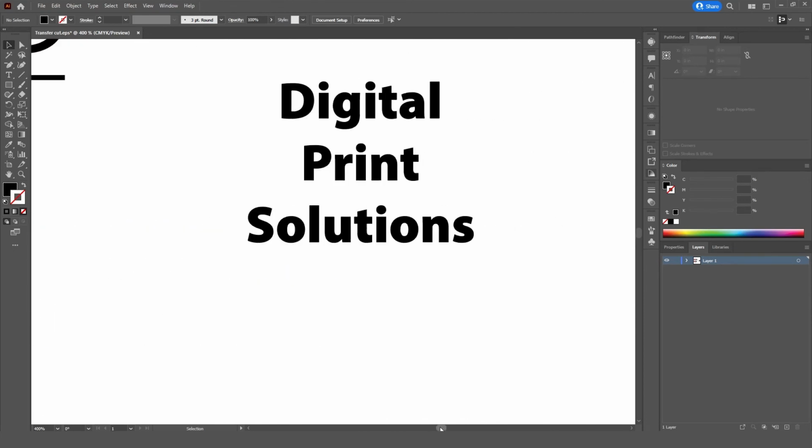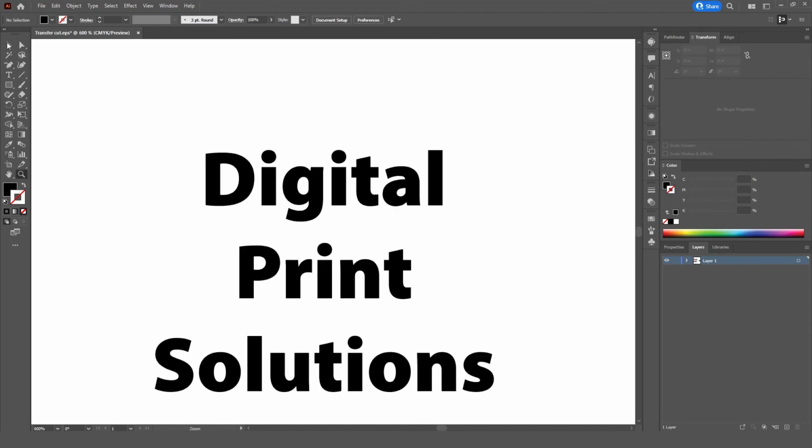The last problem we run into is when we're cutting out the lettering like this. The pixels within the letters can also be too small. In this case, these letters are only about 0.2 inches tall, so the pixels within the letters will definitely not be big enough to cut out. So, we want to make sure all the letters are meeting the requirements and the pixels as well.